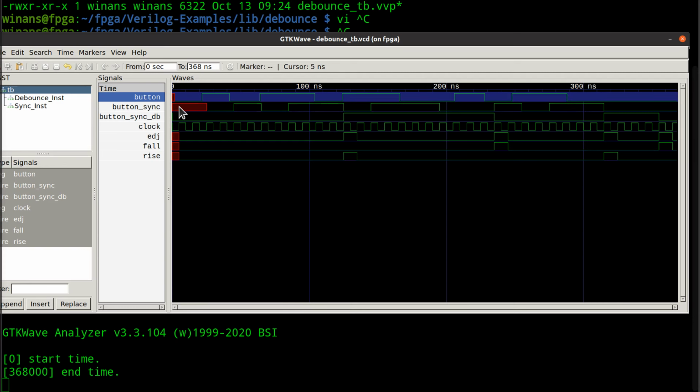We've got undefined stuff here because they don't have a reset signal in this thing. And funny, how do you have a reset signal, which is a push button, that needs to reset the debouncer? Okay, you might have a chicken and egg thing here. So at least one button in your design will probably not be resettable, and that'll be the reset button itself. All right, I'm just saying.